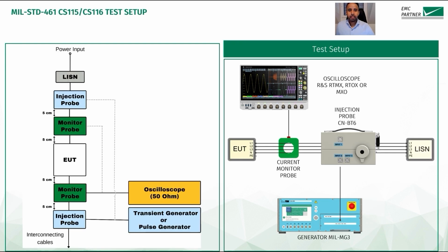The test setup can be performed as shown in the diagrams. The injection and monitor probes are positioned around a cable bundle interface in an EUT connector. The monitor probe is placed 5 cm from the connector, and the injection probe 5 cm from the monitor probe.